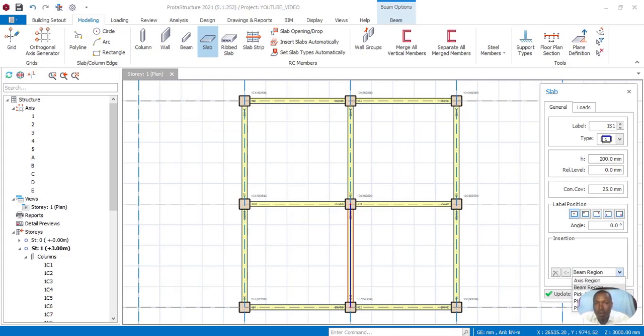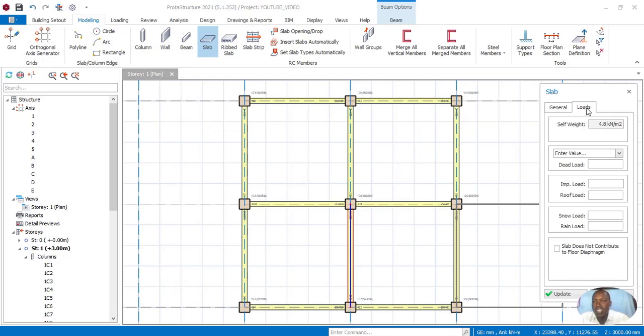We have a beam region where beams cross each other, and we are able to put a slab. Pick axes, we pick them by ourselves. Pick points, we can pick the points. Pick closed slab edge, we can pick any of these we need. And then before going to put our slabs, we have to first go to the loading and reload it.